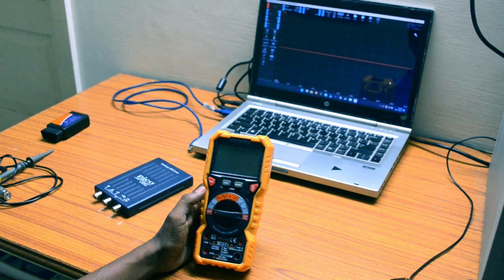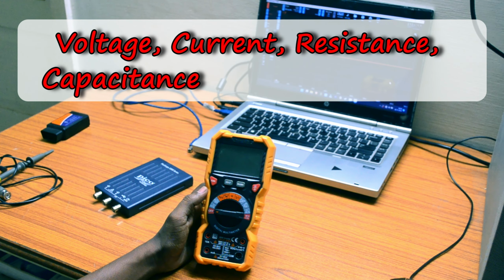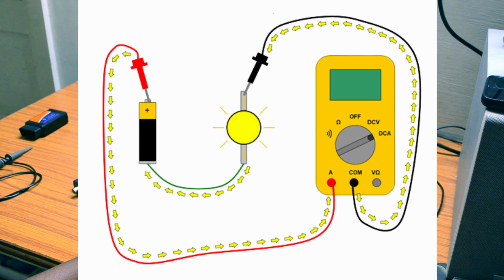By using this tool, you can measure many parameters such as voltage, current, resistance, capacitance, frequency, temperature and other parameters. Basically, the multimeter is primarily used for voltage and current measurements. This first mode is for voltage measurements, and you can see the blinking LEDs, right? One important thing you need to keep in mind is voltages in the circuit are measured in parallel fashion, that is across the components. Current is measured in series.